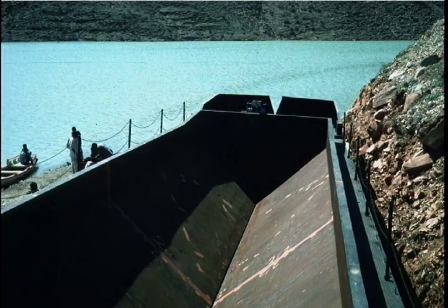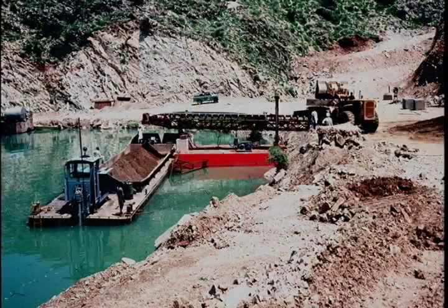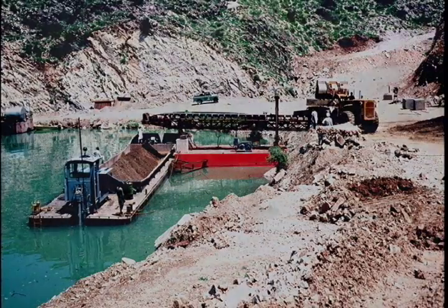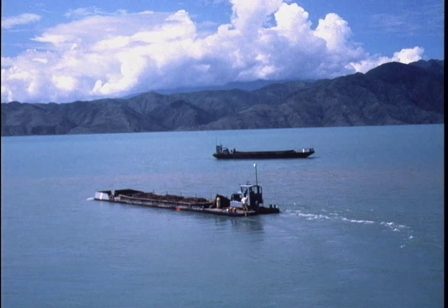The barges used for this operation were of the bottom dump type, as shown in this picture. The barges had a capacity of 105 cubic yards. Side-scan sonar pictures taken after dumping on a sinkhole confirmed that the dump material stayed together as a mass as it sank through the reservoir.